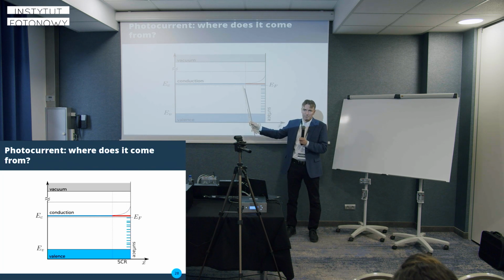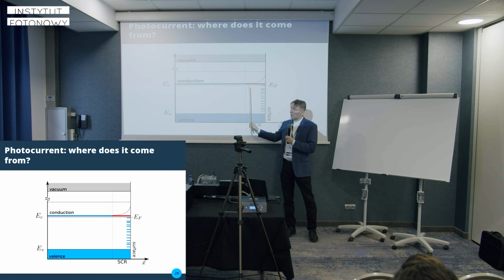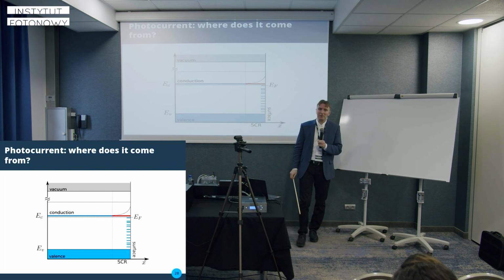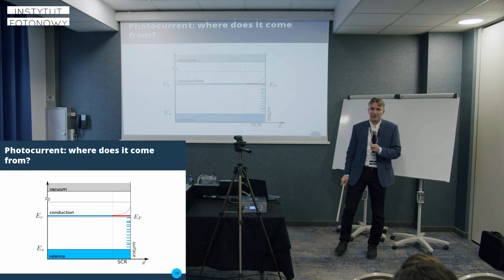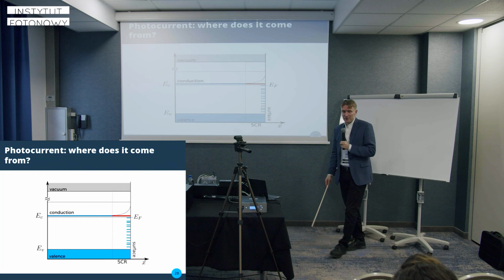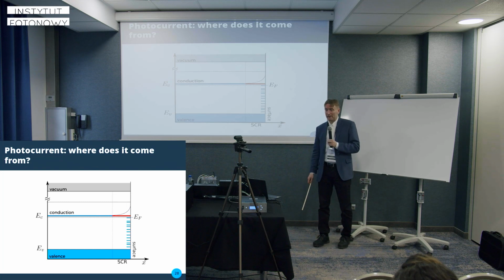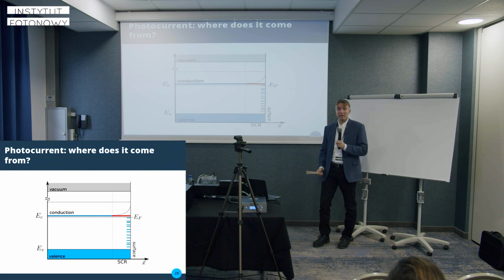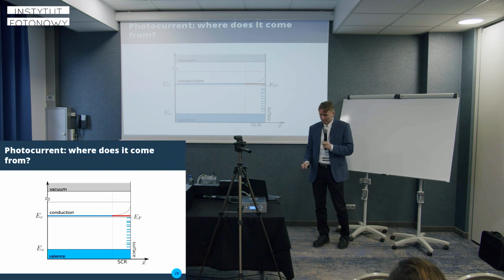They are movable. So you will have a positive or depleted region right at the surface. This region is called the space charge region, and this is a key player in the sample's light sensitivity.